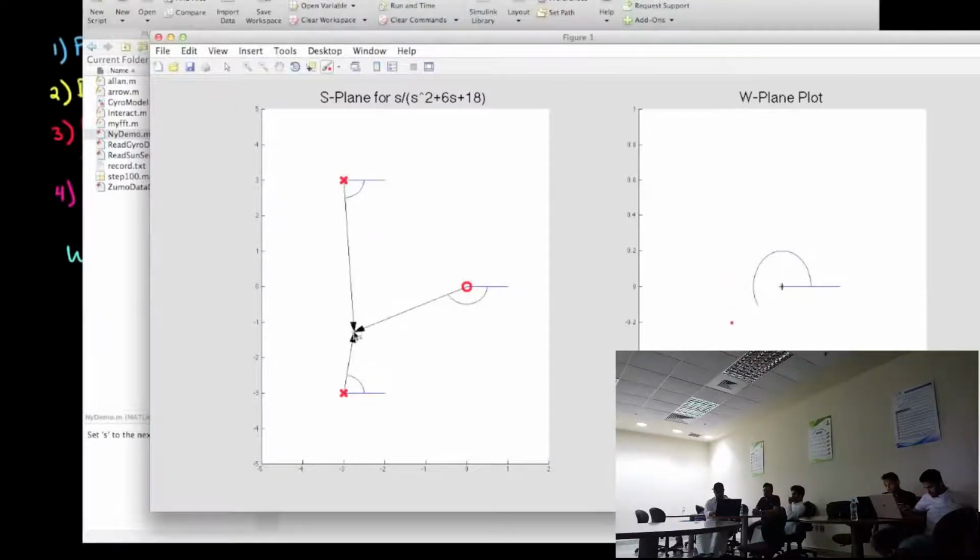And you can see this very clearly on the W plot, that the phase just sort of hovers between 150 degrees and 210 degrees. However, if I do encircle a zero, then as we go along the contour in a clockwise direction, we'll be adding 360 degrees of phase as we move around the zero. This causes the point in the W-plane to rotate 360 degrees in a clockwise direction, like our contour.